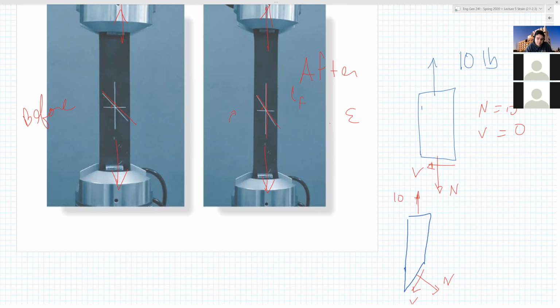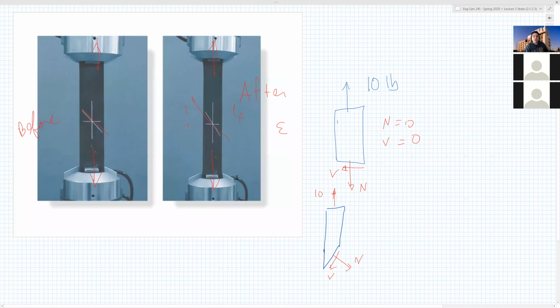Here's the reason why. Maybe the rubber does not fail like that, right? What if the rubber actually just cuts like that? Why did the material just fail like that? Well, because the shear stress is higher there and the material is weaker under shear. Okay, and we'll learn more about the shear modulus and all that in chapter 3. Again, I'm just trying to give you conceptually what's going on. So you have to have a good understanding of how solid materials behave, right? Good?